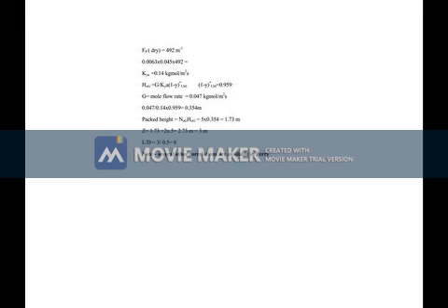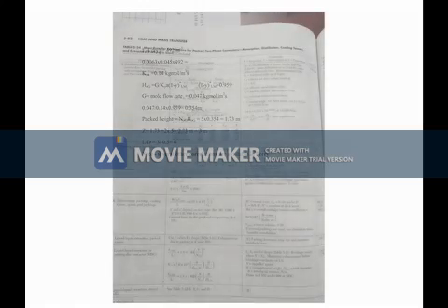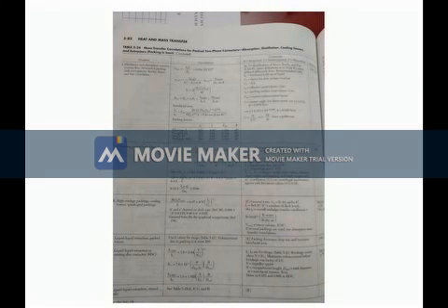The bed density is given, and what we require is this packing factor Fp, dry, which is 492 meter raised to minus 1. I have given a photo of this page. You take the corresponding page and see. Next, we have to find out the number of stages graphically. For that, we have to plot the equilibrium line first.